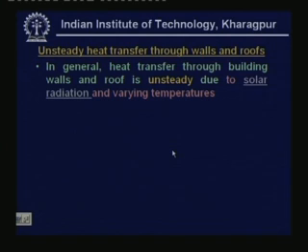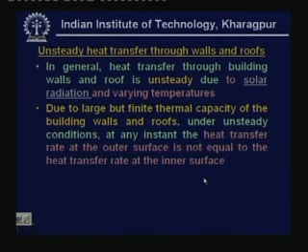Similar to solar radiation, the outdoor temperature also varies with time. As I said, due to the large but finite thermal capacity of the building walls and roofs, under unsteady conditions at any instant the heat transfer rate at the outer surface is not equal to the heat transfer rate at the inner surface. This is very important. What it means is,